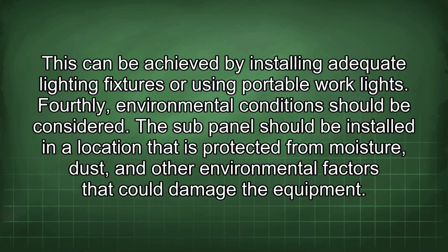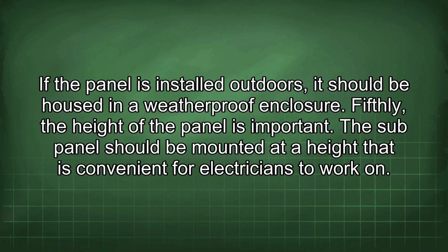Fourthly, environmental conditions should be considered. The sub-panel should be installed in a location that is protected from moisture, dust, and other environmental factors that could damage the equipment. If the panel is installed outdoors, it should be housed in a weatherproof enclosure.